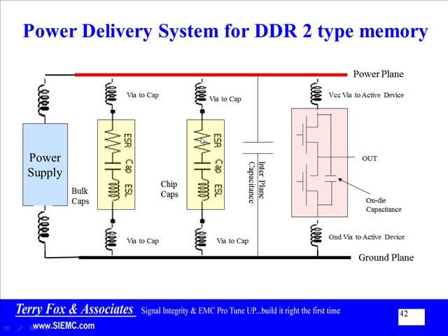But if I have a reasonable number of these capacitors, I can probably get the impedance down low enough, say up into the 250 megahertz range, maybe 300 megahertz range if you have a lot of these on there. But once you get above about 300 megahertz, it starts taking a rather ludicrous number of chip capacitors in order to hold down the impedance.